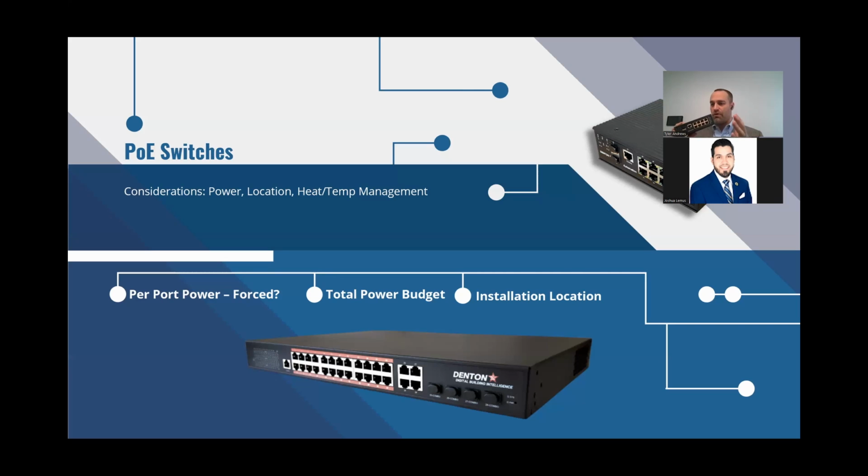And that's a really important thing to know, because you could say, and I'll pull up our 24-port switch, you could say to yourself, hey, I'm getting a 24-port switch. I can plan on plugging a PoE light into every port on that 24-port switch. PoE switches have a total power budget that sometimes doesn't match having 90 watts per port on every port.